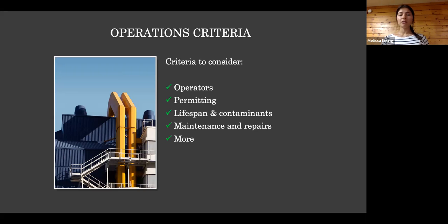Lifespan. I mentioned this a little bit earlier with the materials. There are some situations when you think about, for example, a plastic feedstock that has quite a bit of PVC in it. There's not a lot of technologies that accept a threshold of PVC over 5% of total materials because it creates very corrosive products like, for example, HCl.